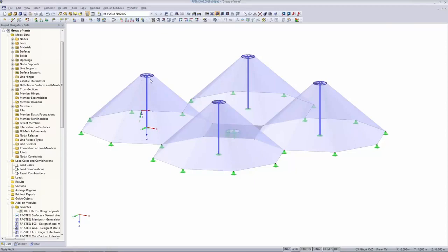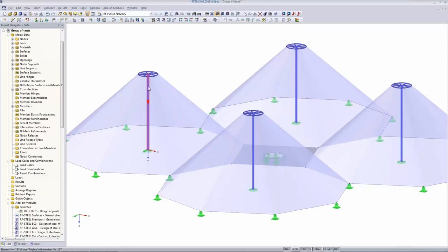And now, the ring on top here is important to avoid singularities. This is something we did already in the first example as well, where we looked at the cone, but I didn't emphasize this as much. It's important that you do not create any singularities up here. If you would build up the cone up to the far top, then you would definitely end up with a singularity, and this is not something we are interested in. It gives failed results. So that's something I will come back to later on, these fixed supports. For now I keep them as they are.